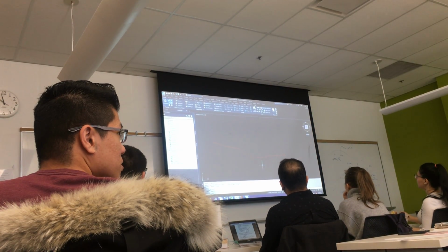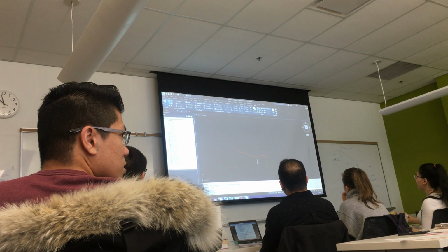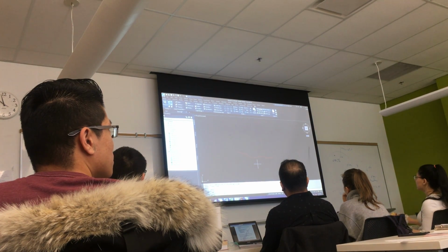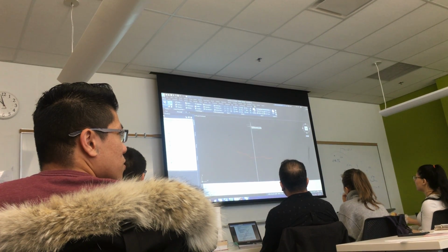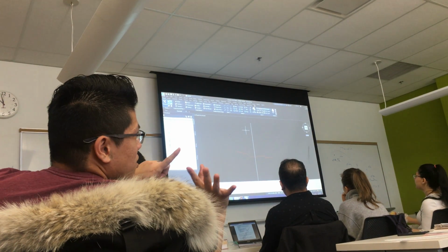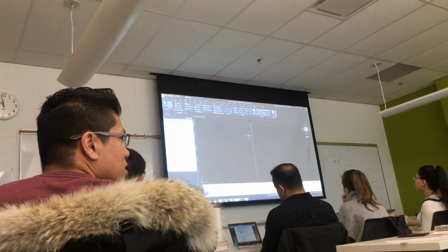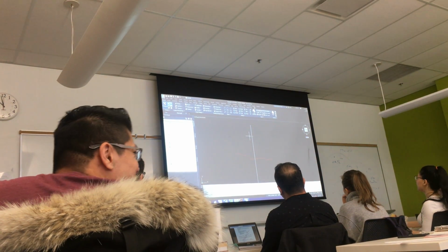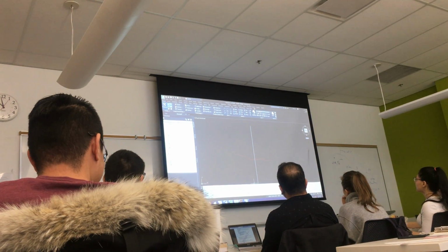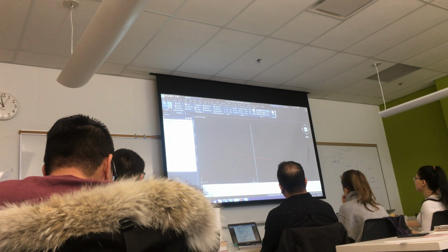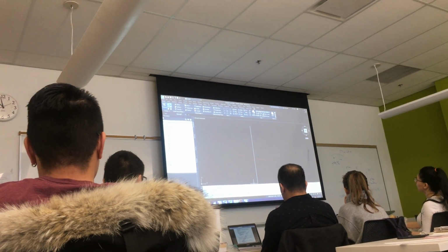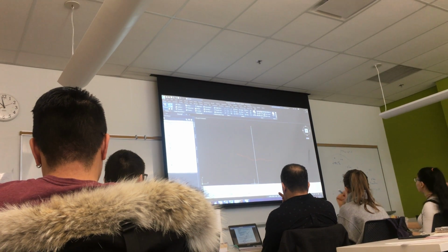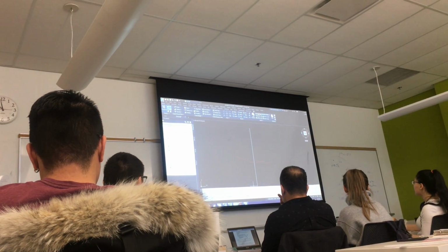Okay. Now, for reference, I'm going to draw the center line. So I'm going to draw a line from 0, 0. I'm going to turn my ortho on, and I'm going to go straight up. So there's the line. These are positive, these are negative coordinates, right? This is the 0 offset. Okay, so if I ID that, you'll see the coordinate is x equals 0. Ignore z, right? I know it's a 3D space, but we're drawing it in 2D. Any questions about how you draw the existing ground?